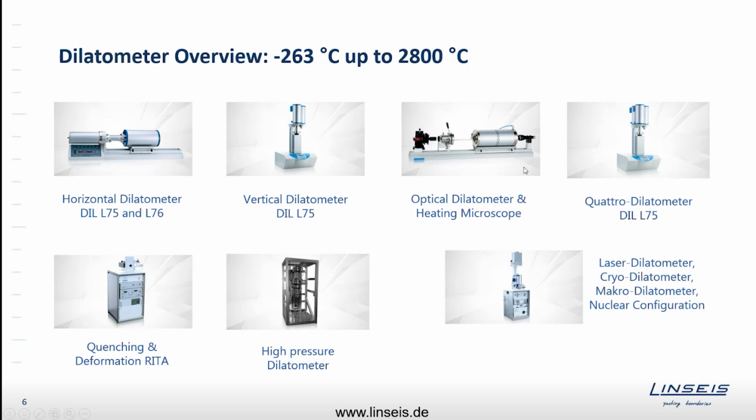We have so-called optical dilatometers, where you have a furnace without push-rod. It's a furnace where you just place your sample on a little platform, and you close the furnace, and then you detect the expansion and shrinkage no longer by touching it with a mechanical push-rod, but you measure the expansion with a camera setup. So you have a high-resolution camera detecting the edge and the shape of the sample and measure it contact-free. The setup was optimized for sintering studies where a force or physical touch could be a disadvantage. Therefore, you can measure it completely contact-free and then can have a sinter study or melting study or stuff like that.